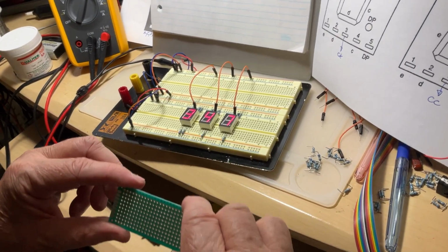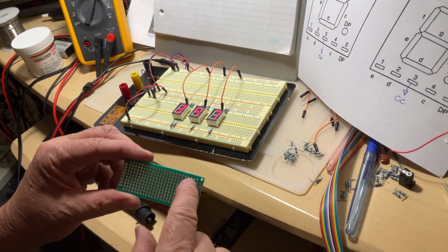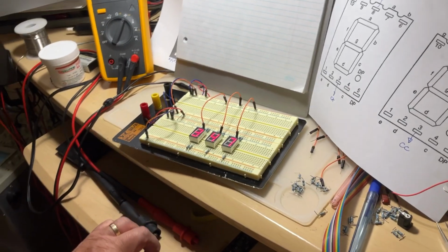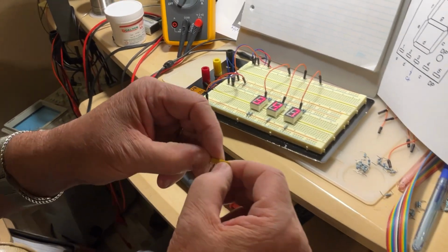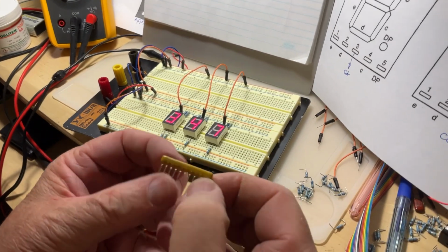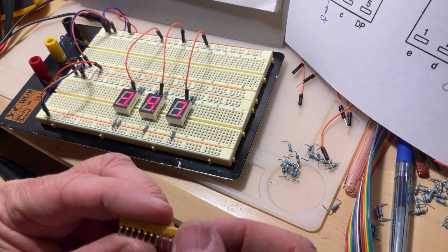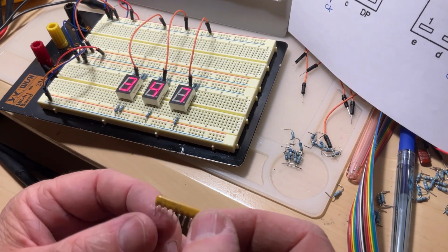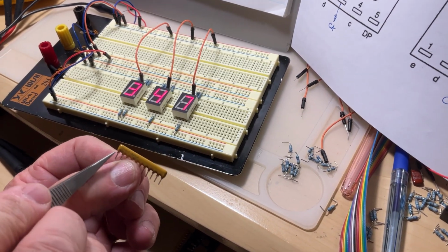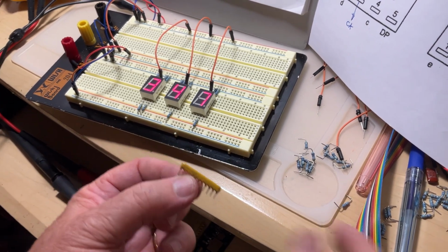However, here we used independent resistors, and it's going to be much easier to use on our printed board another kind of resistor. I'm presenting it to you right now. It's something you may have not seen before. This is called a network resistor. It's a common bus network resistor. As you can notice, right here on the left side, it has a dot. And then, after the dot, you have a number of pins. Take a look what's inside.